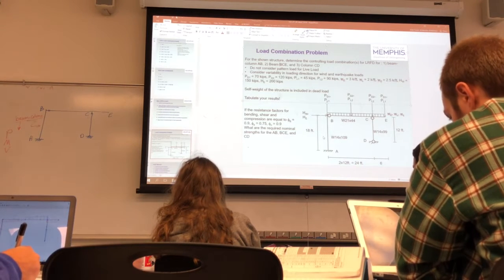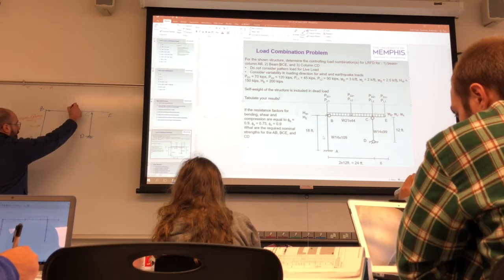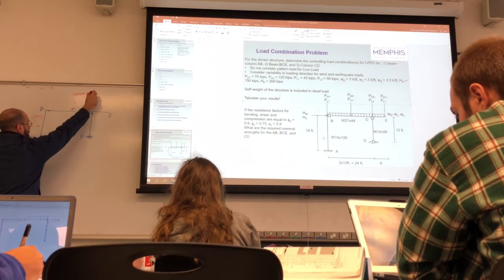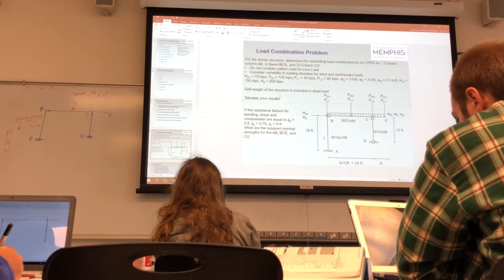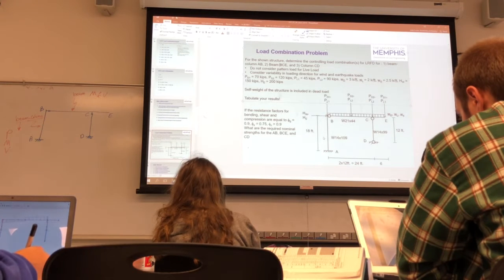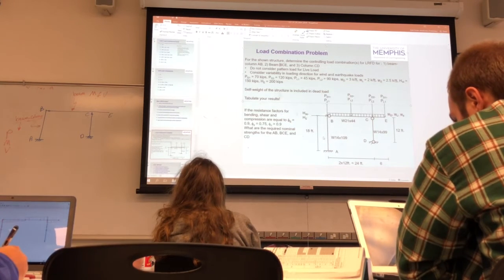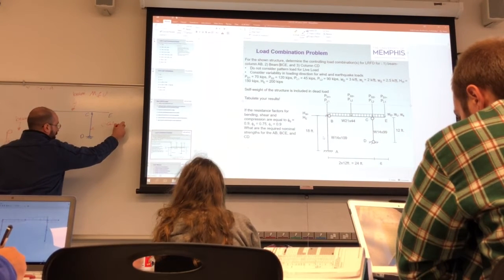If you look at the beam BCE, we call that a beam because it doesn't have any axial, it has only M and V. It has shear and moment only. There's no axial effect. So it's completely different designs, by the way. We'll not cover beam columns completely in steel one; we talk about them in steel two. And then CD is a column, or a compression member.